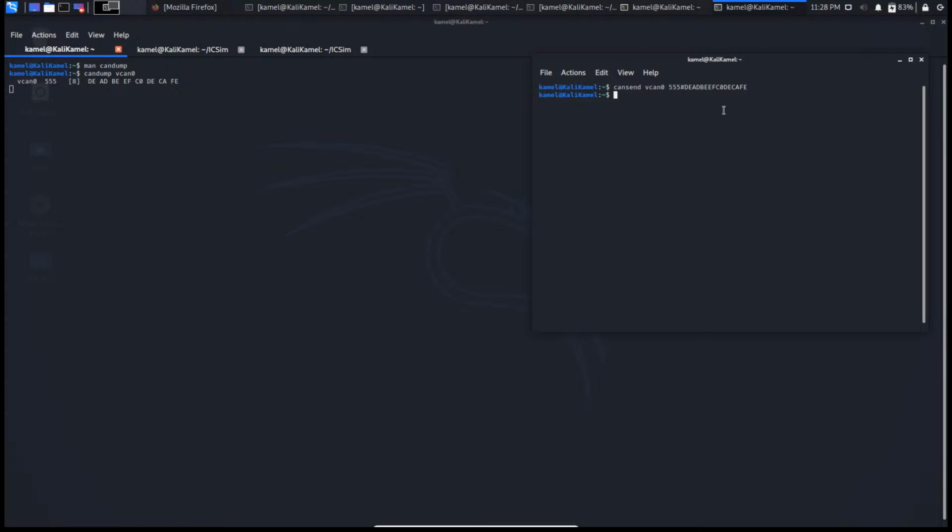You can use these software tools for more advanced programs if you do things like create scripts to actually automate the use of these command line tools, right? But that's a little bit more advanced and not something I can actually go into today. But it is very easy, right? At the end of the day, it's as easy as writing a simple bash script and using the can-utils tools in that script. So you can also do things like delimit your data with a period.